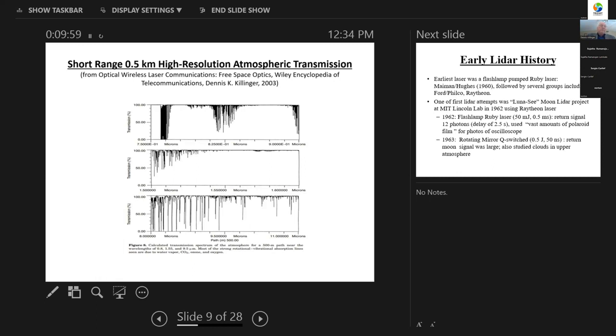And so if you're able to isolate the laser wavelength to one of those absorption lines, and the absorption lines are always around about 1/10 of a wave number in width, you can tune the laser across that absorption line and then measure what the concentration is of the species, which is the DIAL technique I was talking about.